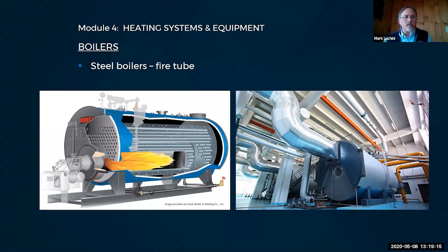So a fire tube boiler, like I said, is the opposite. We have a big old tank. We're sending flame down into a combustion chamber. It gets sent into a series of tubes, back and forth, several passes typically, and then out the flue connection at the end. So if you ever see a big tank like this, you can point at that and say, hey, that's a fire tube boiler. People think you're really, really smart.